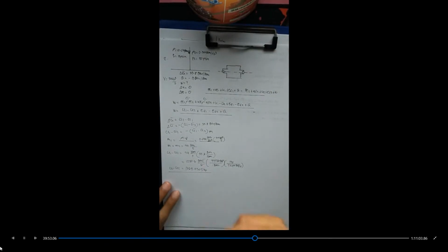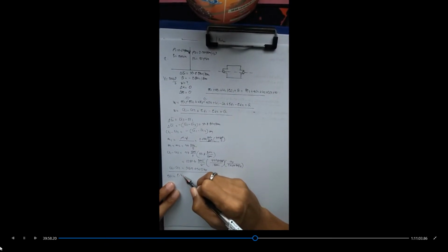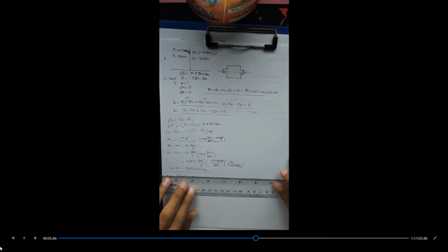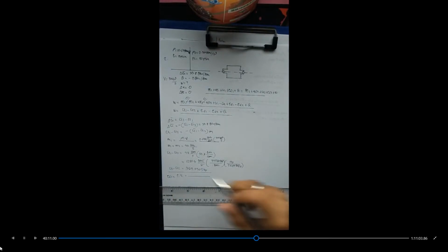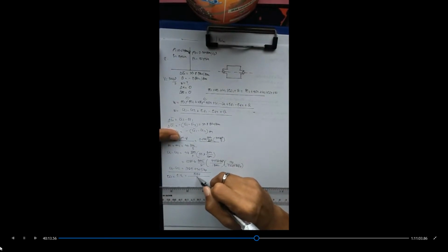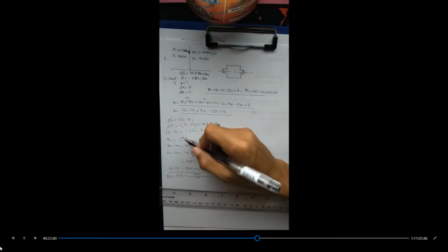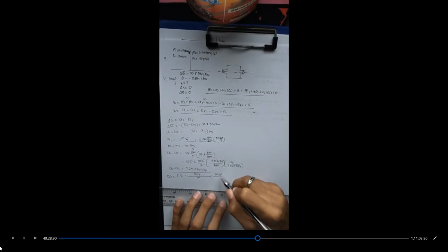That's it. Now we are going to solve for our flow work 1. Flow work 1 is equivalent to pressure 1 times volume 1. Our pressure and volume are given, so we just have to substitute the given values. Pressure 1 is 15 pound force per inches squared. Then our volume 1 is 500 cubic feet per second.